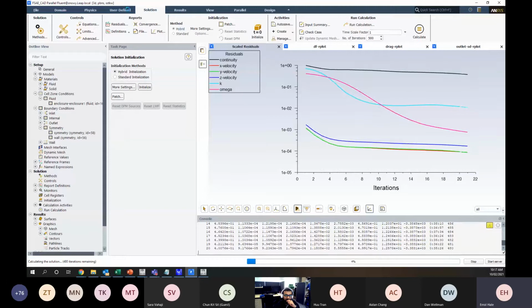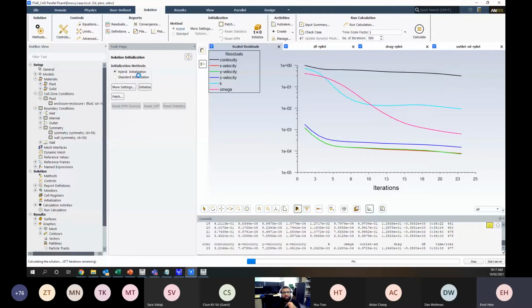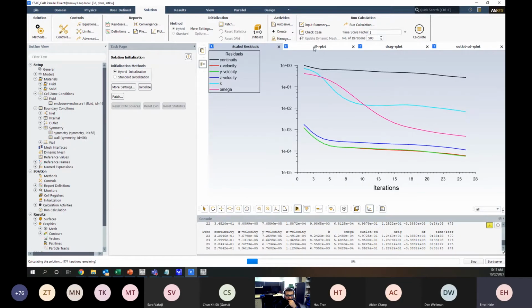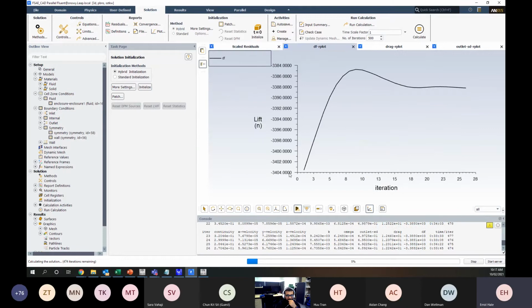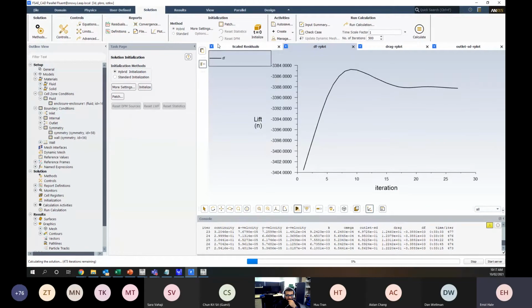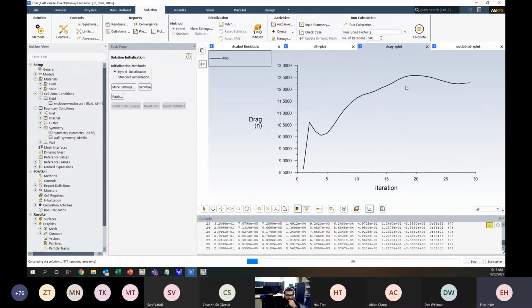And we can do things like change the under-relaxation factors, the timescale factor, which is the pseudo-transient relaxation factor, or the other under-relaxation factors which were in here, pressure, velocity, etc. But often, it's not always going to be a guarantee that we get a converged solution. The other way that we can assess convergence is through these monitor points. Obviously, if these monitor points are still jumping around all over the place per iteration, so it's not converged to a solution, then maybe we need to do a bit more work to get a solution converged.